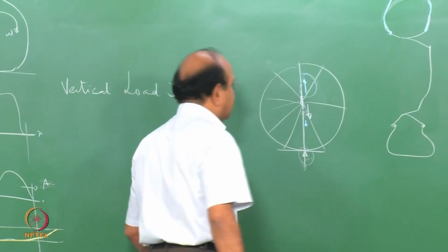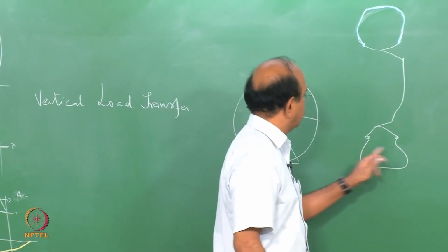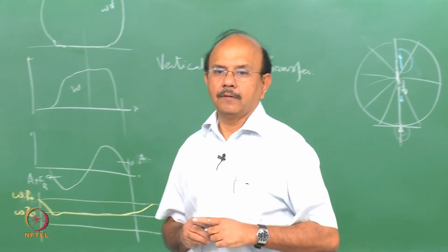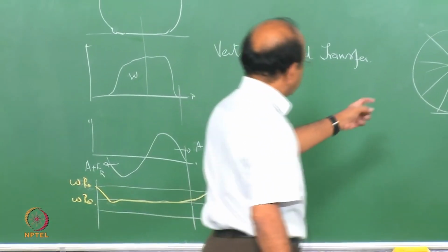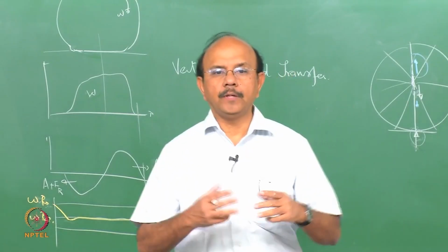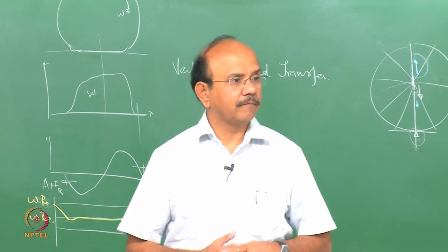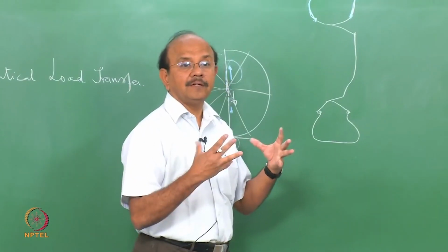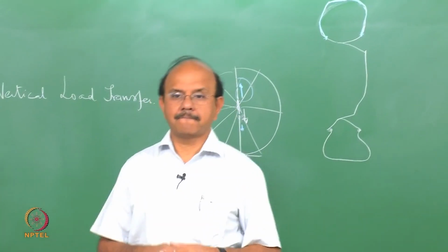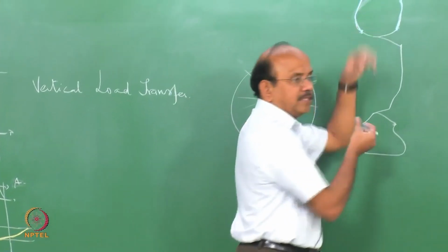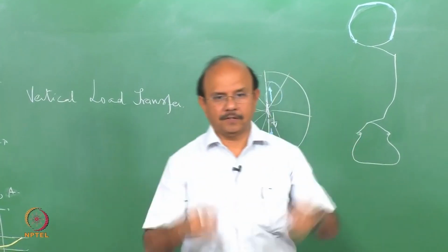Now this sidewall is going to act like a spoke. Here the tension in the spokes is given when we assemble the wheel. Here the sidewall gets the tension from the pneumatic pressure, in other words, the inflation pressure.